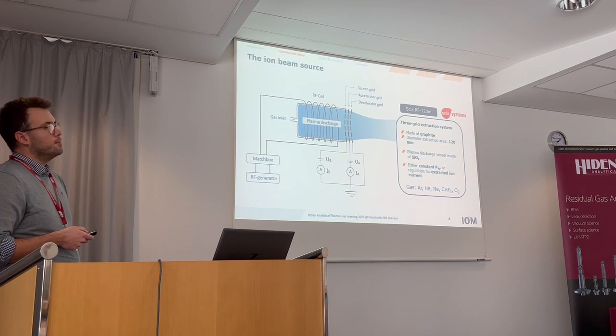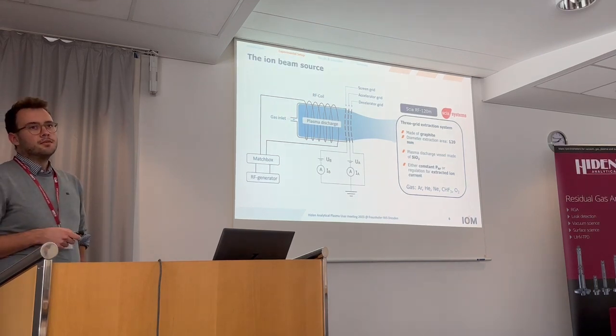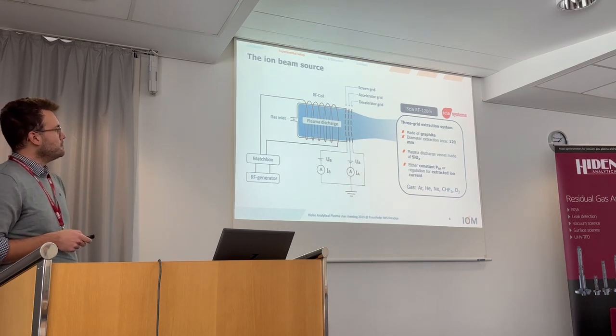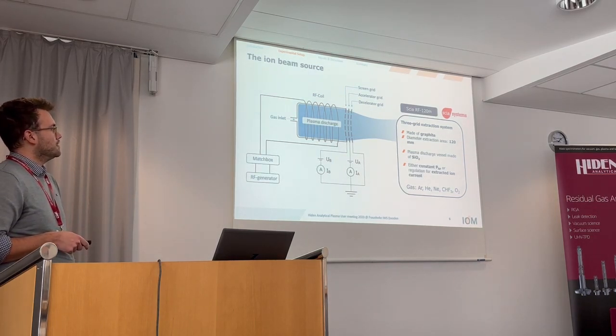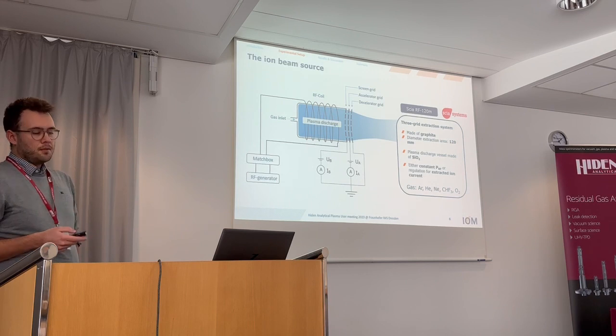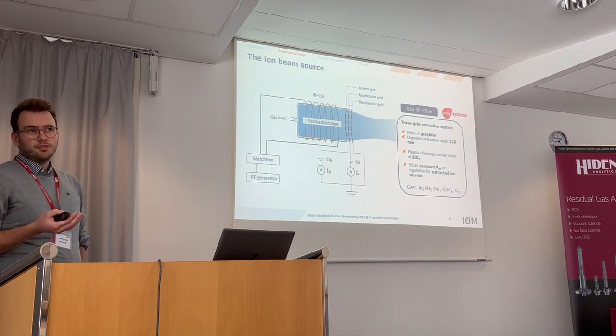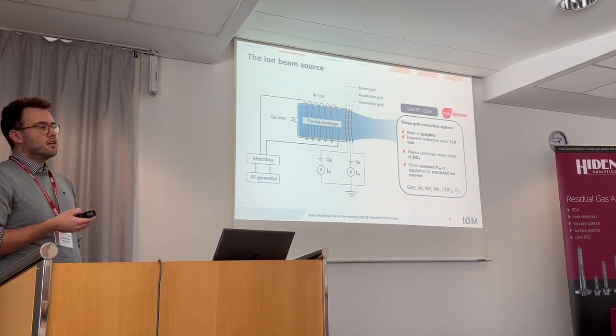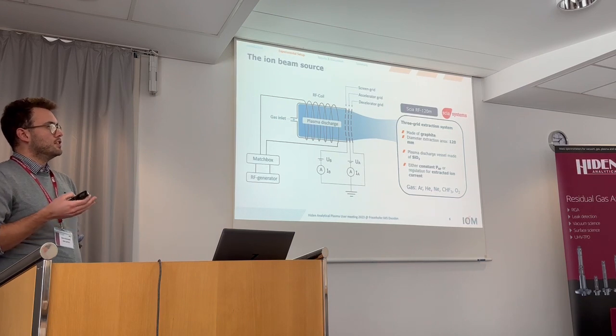We are using a commercially available ion beam source from SPA Systems. It's a company here in Saxony in Chemnitz, and we are mainly using different gases, argon, so different noble gases, and our standard mixture for etching is trifluoromethane and oxygen. But this mainly depends on what you want to etch and how you want your result to look like.